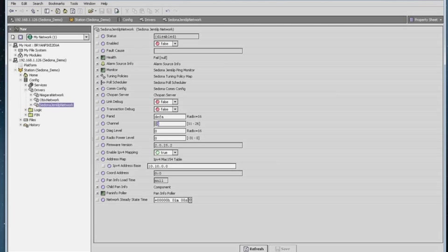All right, the next step would be to select the channel. You can see here that channels available are 11 through 26. There are 3 channels that operate outside of any standard 2.4 gigahertz 802.11 or .15.4 frequency, and that's channels 18, 25, and 26. So I typically utilize channel 26. The next would be to select your PAN ID.